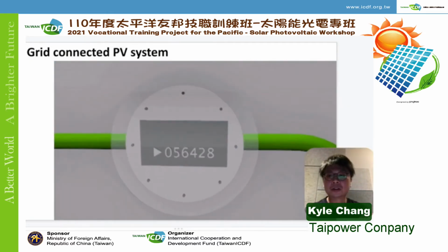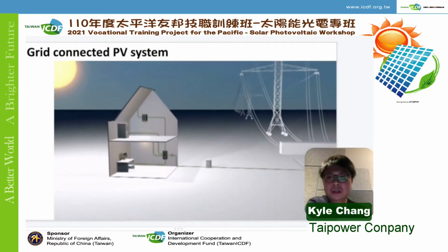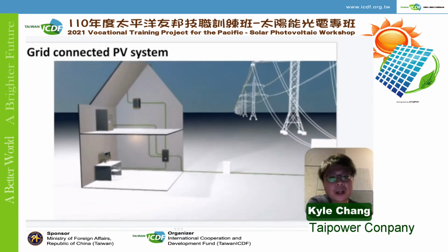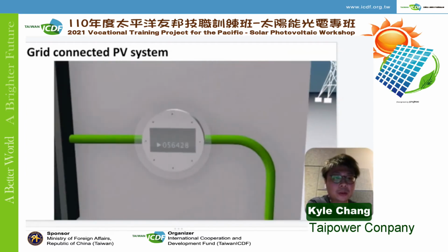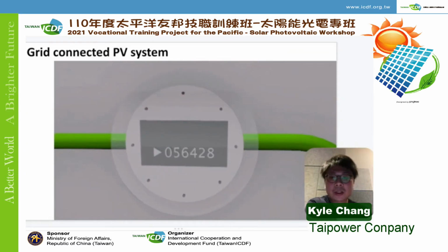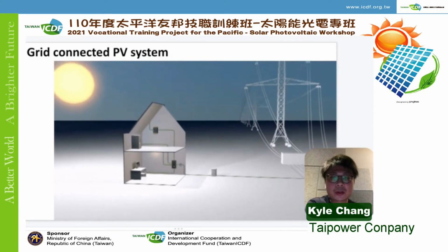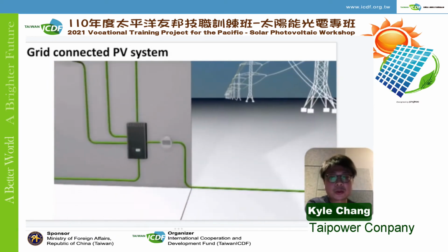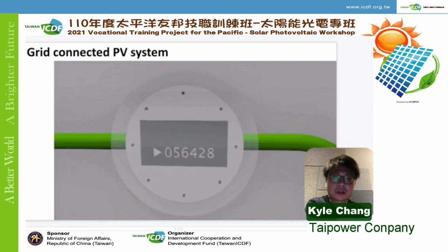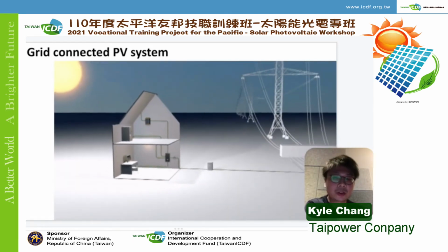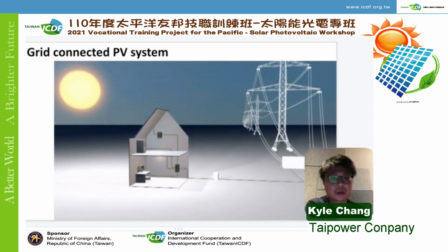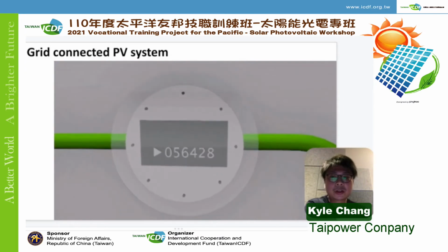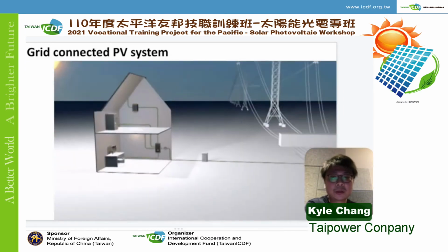And on a different day, if it is a very sunny day, the PV system is providing much higher power than what the load requires. Under such condition, the AC power is fed to the grid. In most countries, I think the customer can offset his electric bill in this method, and this facility is called net metering.